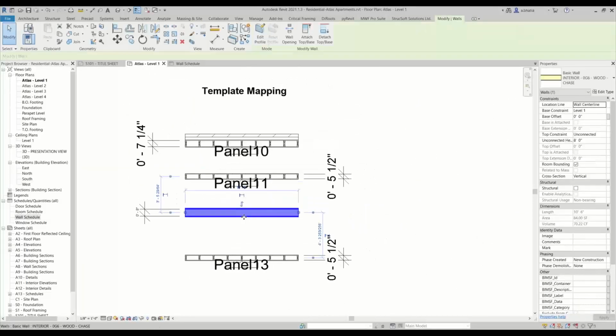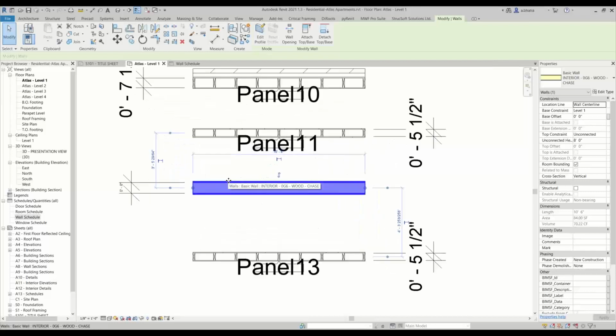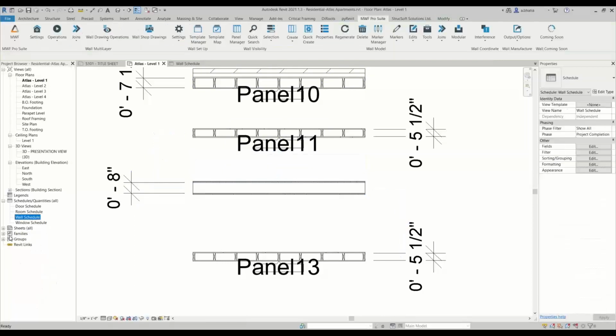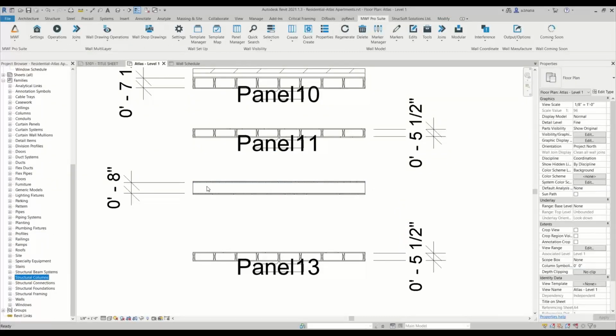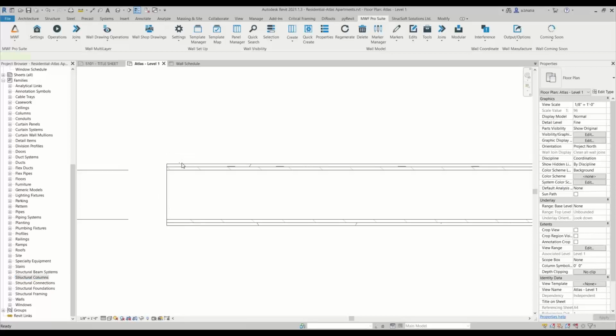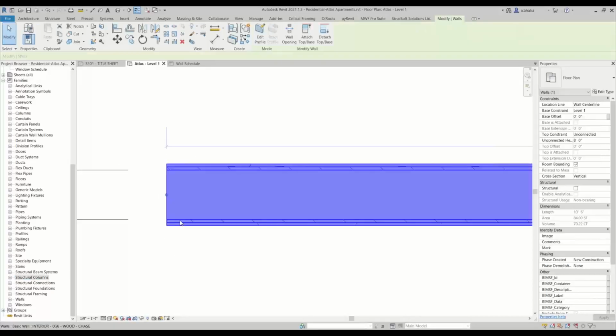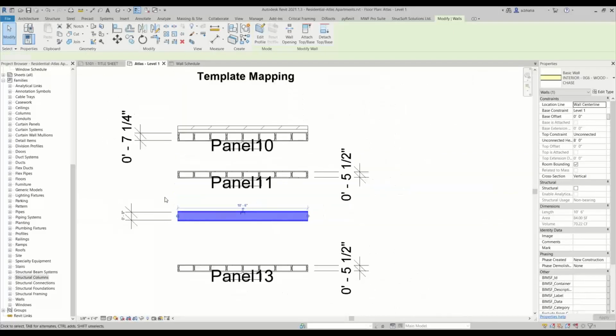So what I'm gonna do is click on this guy, and I'm gonna see if my structural layer thickness is okay to fit with the largest studs that I need to place in there, right? Let me just quickly do that. The reason I'm doing this is because I want to make sure that my end studs actually fit within the wall thickness. And if you didn't do that work in the past, then you'll have to do it now.